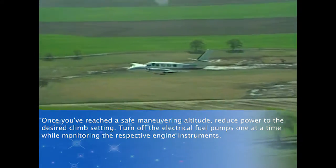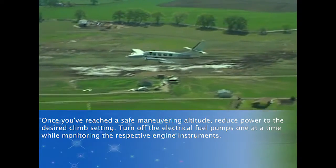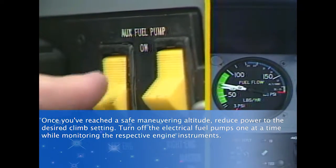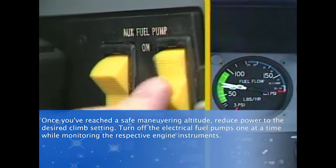Once you've reached a safe maneuvering altitude, reduce power to the desired climb setting. Turn off the electrical fuel pumps one at a time while monitoring the respective engine instruments.